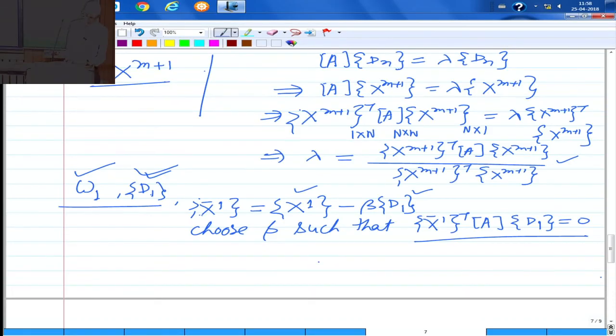So at the end, whatever vector you get, let us say x bar m plus 1, would be proportional to d2, because there is some constant you can always arbitrarily assign. This is after multiplying the vector by matrix A m times. So the resulting vector is going to be d2, and then you use a similar kind of formula to get the second lambda, corresponding to omega n2.